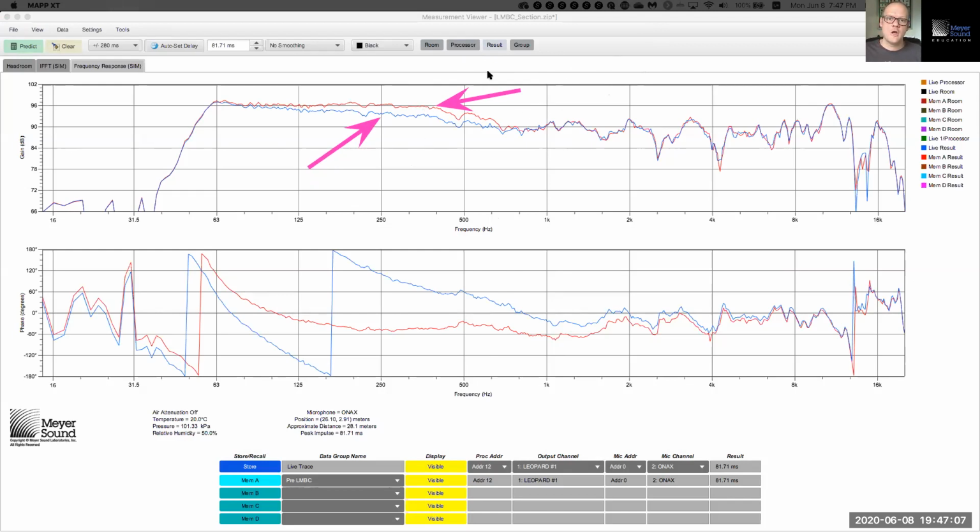This we already knew, but now you see the price that you pay for using all pass filters: due to the all pass filters, we have gained a phase wrap, because that's the price you pay for all pass filters. So we have a little bit more phase shift.